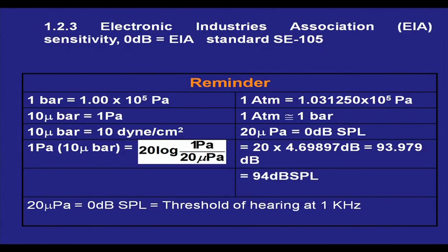Now, in these lectures we will investigate in detail what we mean by the sensitivity of a microphone, how microphone sensitivity is defined, how it is measured or determined, and then we will discuss what will happen if a microphone is connected to the preamplifier, in which condition it will deliver the maximum power, and what the standard sensitivity defined by the Electronic Industries Association (EIA) is.